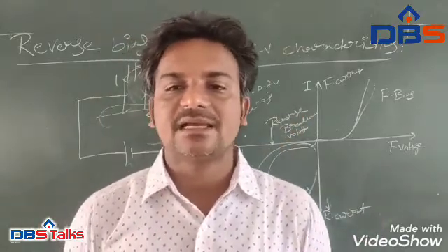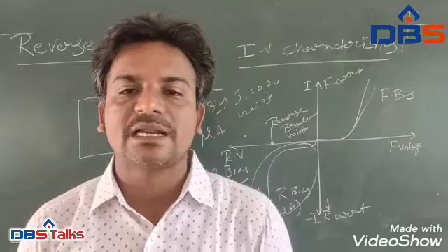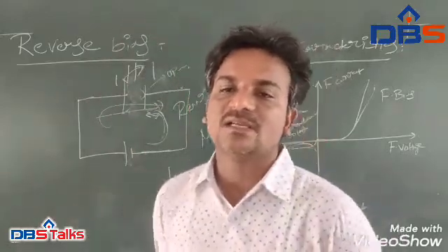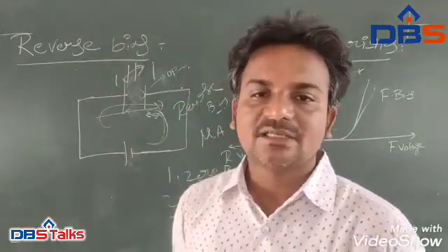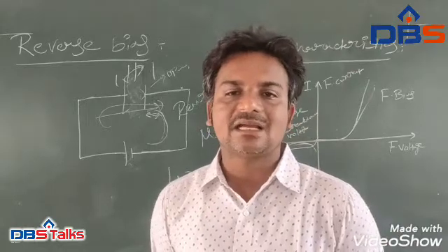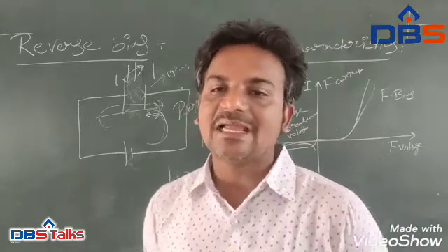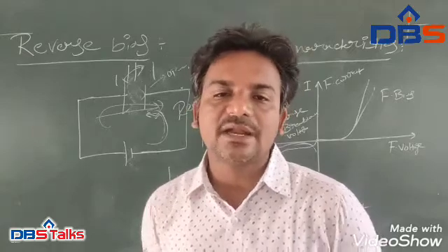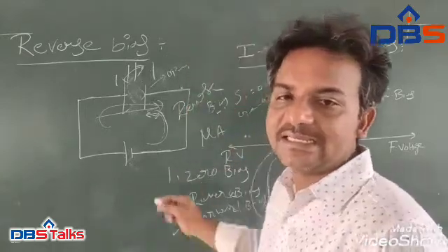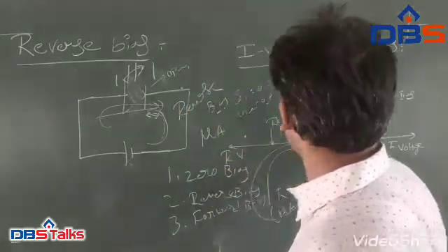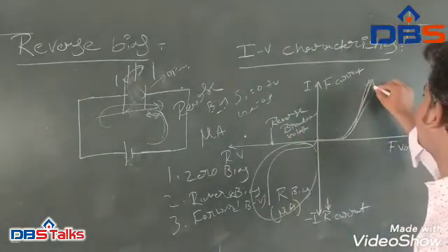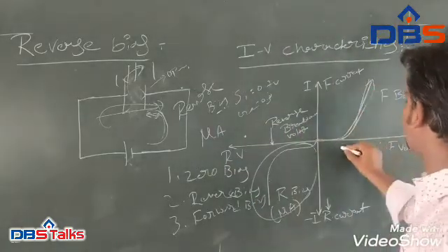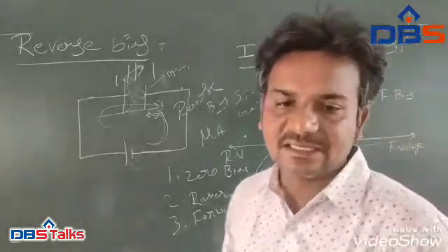This results in the characteristic curve of zero current flowing up to this voltage point. It is called the knee on the static curves, and then a high current will flow through the diode with little increase in the external voltage, as shown below. So the current will linearly increase when the voltage increases.